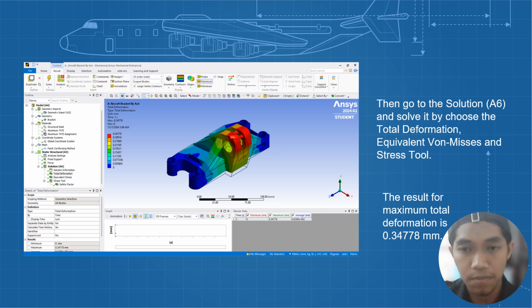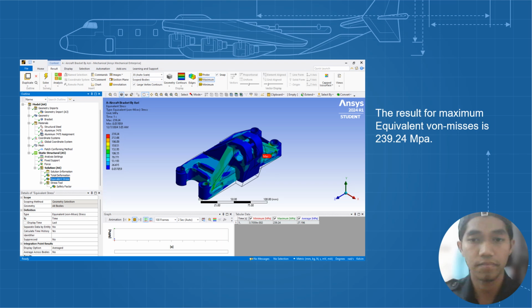Here is the result for maximum total deformation, which is 0.34778 mm. This result was lower than the original deformation, which is 0.43 mm. Here is the result for equivalent von Mises stress, which is 239.24 MPa. For this result, the stress is not required for me to analyze, but I expect that the stress is not high from this value, like 300 MPa and so on.